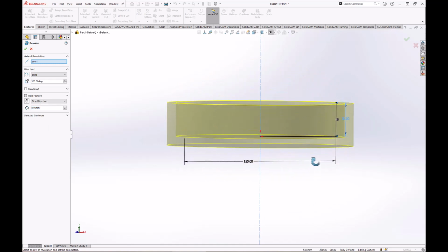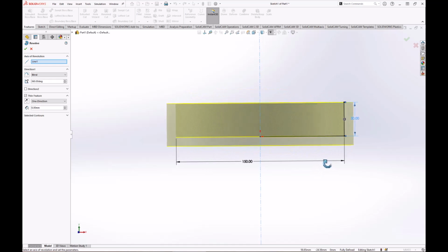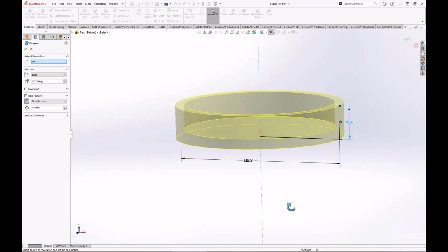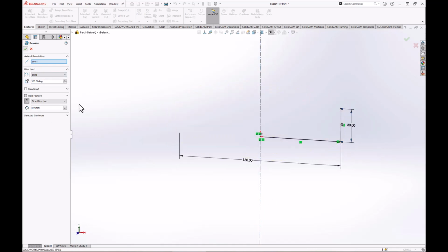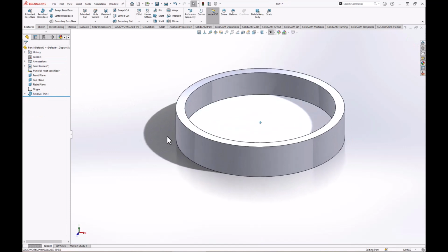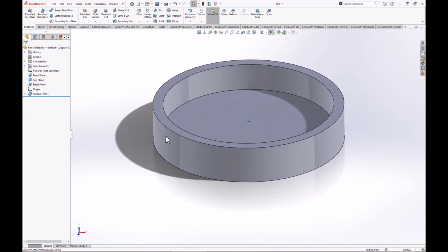And just to be clear what's happening here, if I view the sketch almost flat to the plane that I sketched it on, it's added 8mm of wall thickness to one side of those lines that I sketched. As it happens, it's picked the outside, and that's not what I want. So I'm going to click on this button to flick it to the opposite side. So you can either have it on the outside of the line or the inside of the line. In my case, I want it on the inside like that. So that's our basic shape that we need to begin this part with.